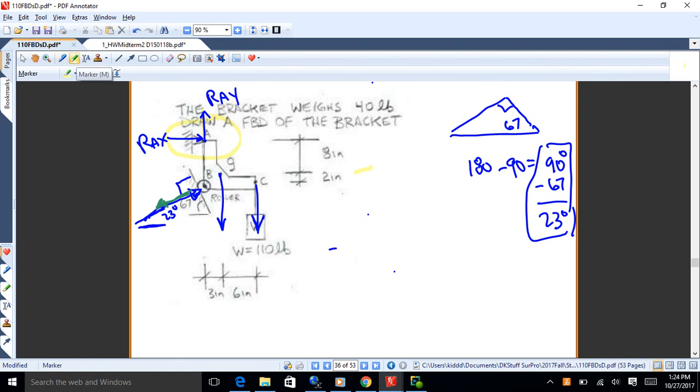All right, so what I meant earlier, don't think too much, is when I see a pin joint, I put an X and a Y force on there, and that's all I think about. I don't think about anything more. I see a roller, I put a force in there that's normal to the flat surface. I don't think about anything more, I just do that.